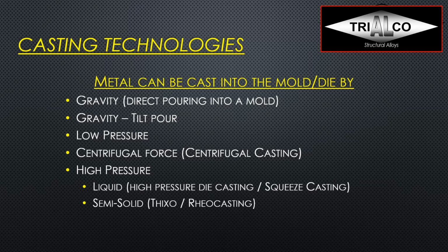And there we distinguish between liquid high pressure die casting, so that's the typical high pressure die casting we know, or if we inject slowly and squeeze the metal more, that's called squeeze casting. And then semi-solid casting, and here again we distinguish between Thixo and Riserless casting.